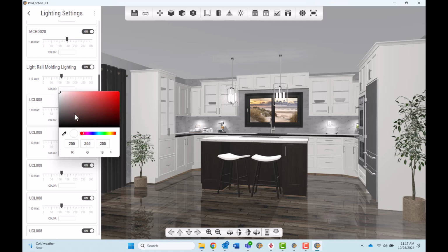the word Color to open a color gradient selector. Left-click and hold the slider at the bottom of the color control panel. Drag to the desired hue. Then, left-click within the gradient above to see the color in the sample preview area.